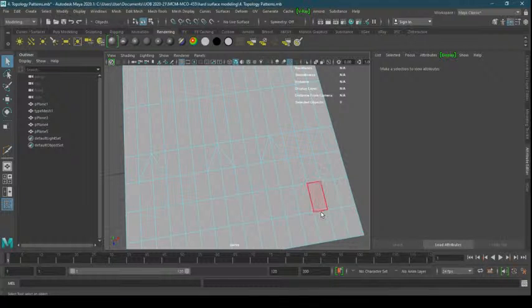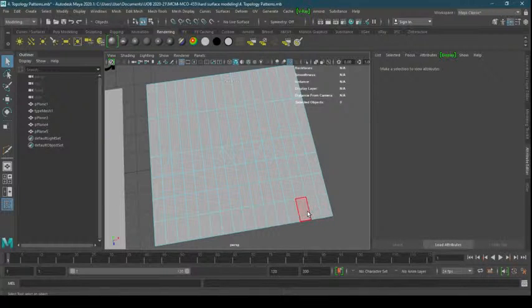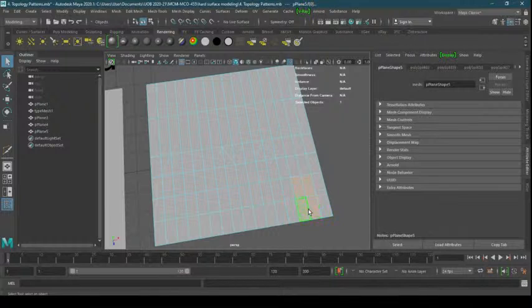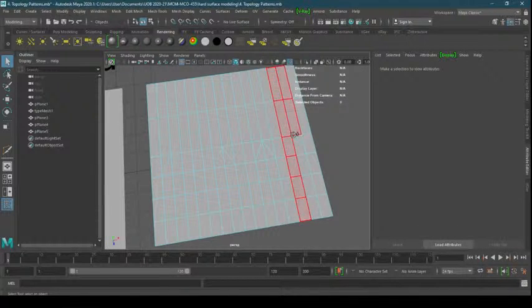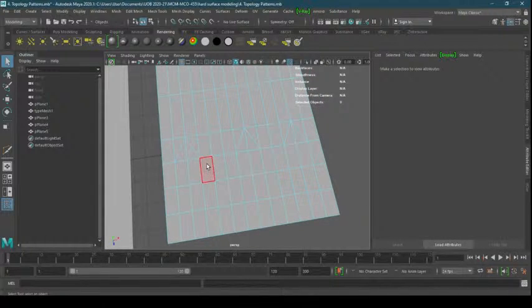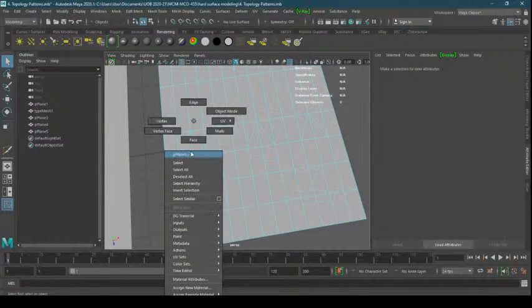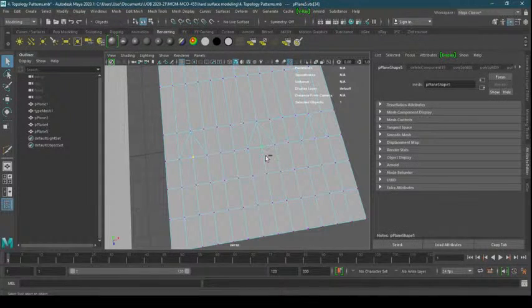Take the faces. With the tab key I can click here and then drag my selection. Oops, what happened? Okay, so I will make a selection, press delete, it's gone. Now I have these diamond shapes over here. They don't look like a diamond right now, so I can go to the vertices, take all these verts from here, press W and slide them down.